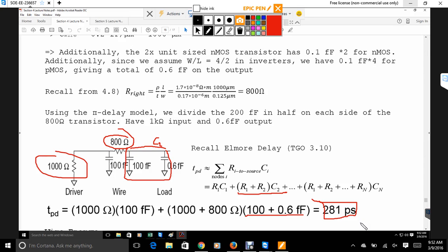So basically, all you would do in this step is, instead of 4/2, figure out how the inputs relate based on the number of inputs. You plug that in, and other than that, it's the same thing. Because you have one output driving, each input on the NAND gate is going to drive one PMOS and one NMOS transistor, right? So it's fundamentally the same.